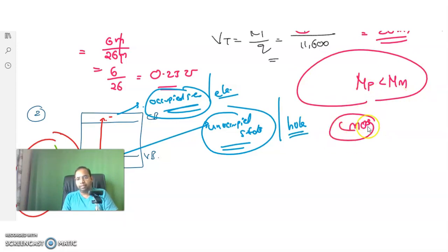In the CMOS logic family also, generally we are constructing the circuit with the help of N-MOSFETs and P-MOSFETs. But the speed mismatch will happen. Why is the speed mismatch happening? Because the mobility of electrons is more. That means the N-type enhancement MOSFET will switch very quickly compared with the P-type MOSFET, because the mobility of holes is less. So to match up the speed, we are doubling the size of the P-type MOSFET in the case of the CMOS logic family.